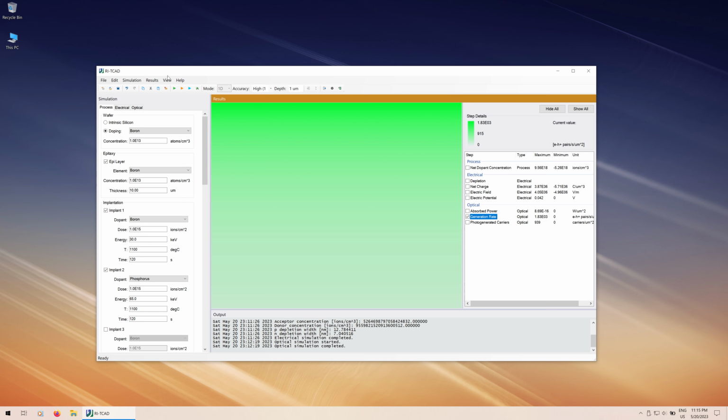And then if I go again to our transparency mode, and if I do depletion, you see that tiny sliver, I will turn it on, turn it off, turn it on. It happens here, so only the intersection of that sliver and the generation rate layer is what finally contributes to the signal that we are getting.